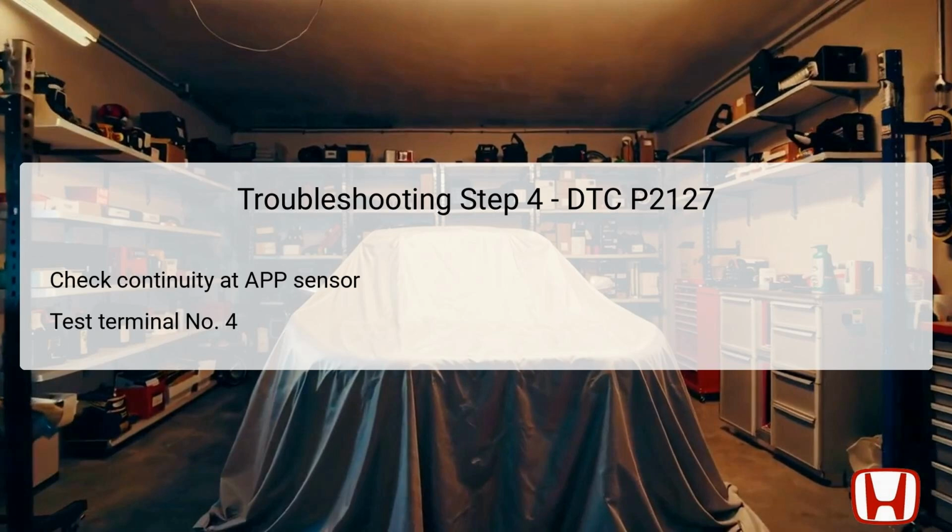In this step, the technician will check for continuity between APP sensor 6P connector terminal number 4, APS-B purple wire, and body ground. This is a critical test to confirm whether the ground connections are intact and that there are no breaks or faults in the wiring leading to the APP sensor.